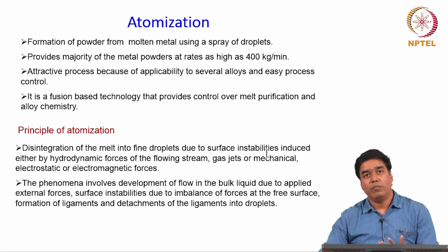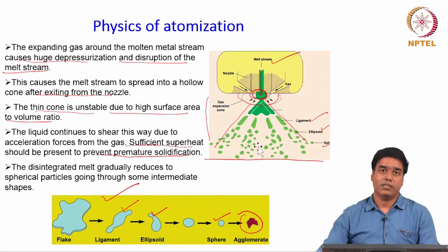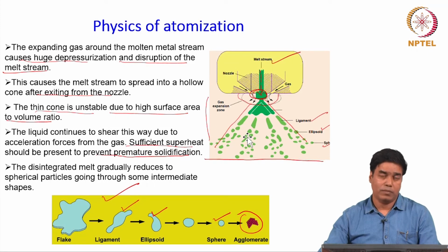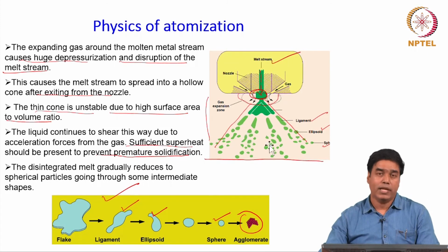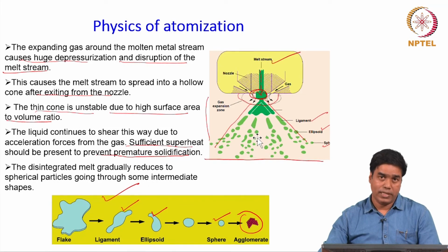And what will be the shape of these droplets would depend on certain parameters, for example, the superheat and the solidification time, which is allowed here for this liquid stream to finally solidify after these droplets are created inside the chamber.